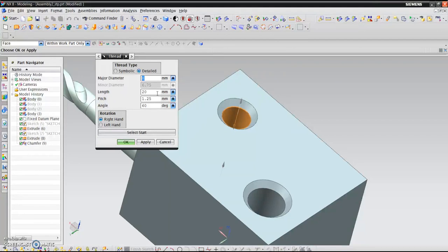If it's a titanium aluminum nitride coating, since it's aluminum, you cannot use that coating on aluminum blocks or aluminum workpieces, but you can use a titanium carbonitride coating on taps. All the tap manufacturers, if you look at the illustration, give taps a color code. Each color represents what type of workpiece it will be used on, starting from low carbon steel, medium carbon steel, high carbon steel, high strength steel, heat resistant steels, high strength alloys, you name it, different titanium, stainless steel, different types of stainless, 300 series, 400 series.